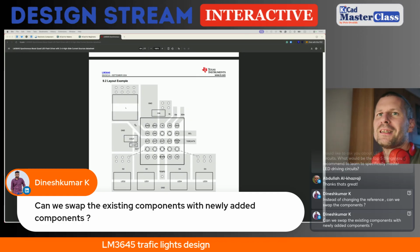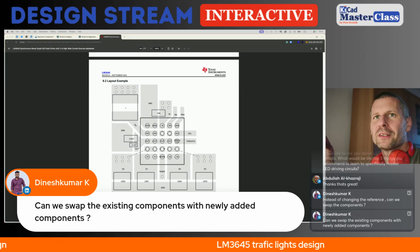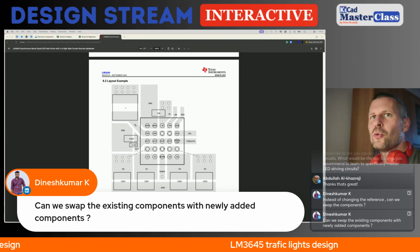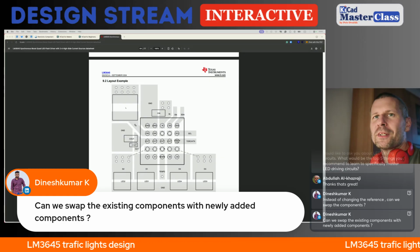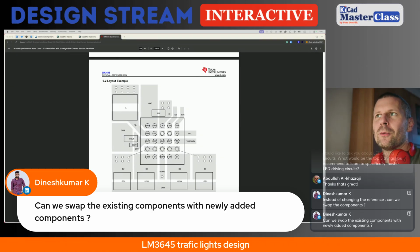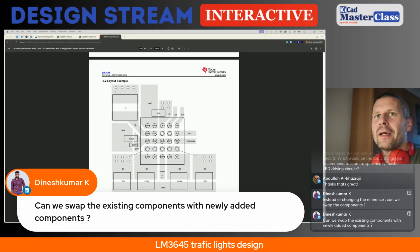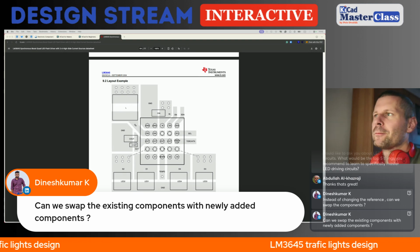What I did was change the reference designator of the newly created components to the ones from the schematic. The newly created components had unassigned new designators, and their representation on the schematic was 0. They were not on the schematic. So I think the most straightforward way was, as I did, to edit the designators with the existing ones, because the newly created ones were extras. Yeah.